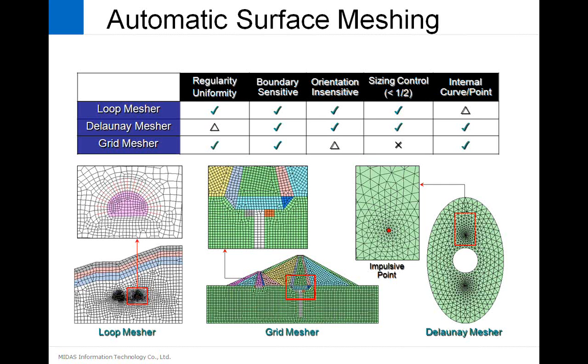So you can mesh different solids using a loop mesher, a grid mesher, or even taking care of center points using Delaunay mesher.